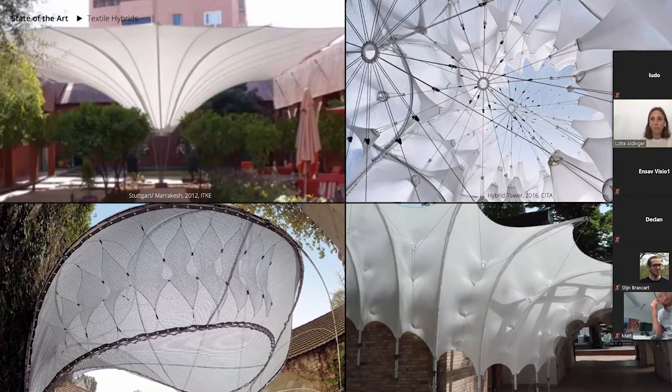So basically what is demanded here is a reinforcement strategy, which can be either volumetric or through adding additional layers. And here comes in basically my belief that bending active tensor hybrids can be very suitable as a formwork system themselves.